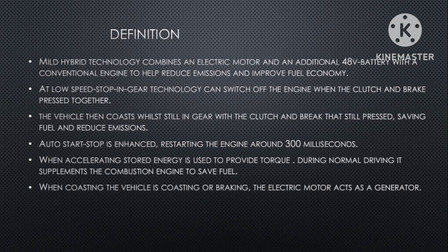The vehicle then coasts while still in gear with the clutch and brake still pressed, saving fuel and reducing emissions. Auto start-stop is enhanced, starting the engine in around 300 milliseconds, and when accelerating, stored energy is used to provide torque during normal driving. It supplements the combustion engine to save fuel.